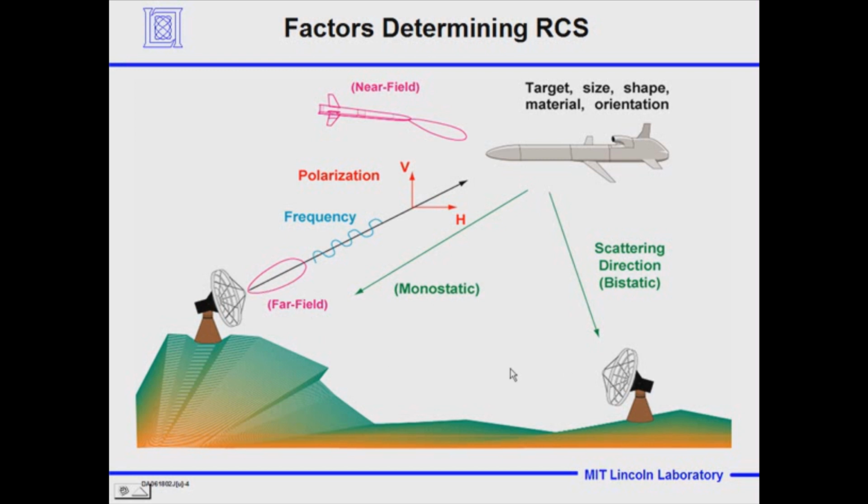So you're going to have to put in both of these orientations, both of these locations relative to the orientation of the target, and therefore the bistatic cross-section data would be a lot bigger. There wouldn't be just a cross-section number when you're looking nose on. There'd be a cross-section number when you're looking nose on, and different sets of angles off the side. It's another whole parameter you'd have to worry about.